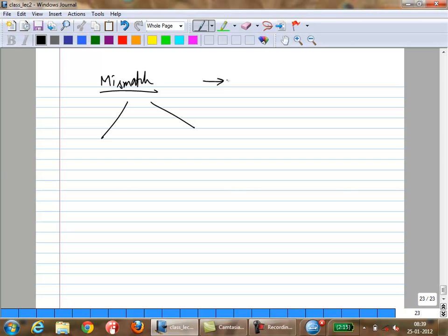Similarly, if you have an op amp gain stage like this, let's say you want an exact gain of 2, right? If you want an exact gain of some n, R2 should be n times R1. Correct? So there are cases where you want them to be identical. So let's say if the gain changes from the actual value, that could be a problem for your circuit. So that is called mismatch. If the two are not identical, that's called mismatch.